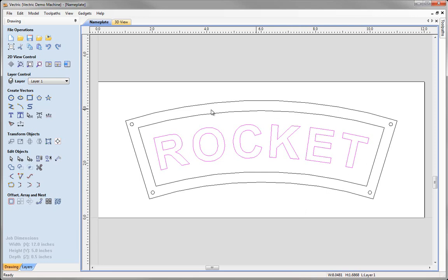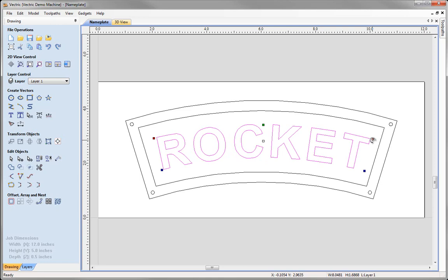And the other thing that's a little odd about the text in this case is because of the space of the T here, the gap here looks a little strange from the side of the R to the side of the T here. So I may want to go back into the Edit Text Spacing and Curve option. I may want to just close up the gap for the R there, and if I click on this red node here, what I can do is just drag this around.